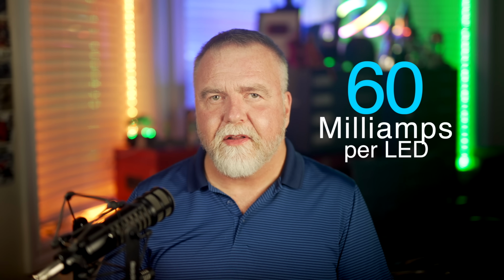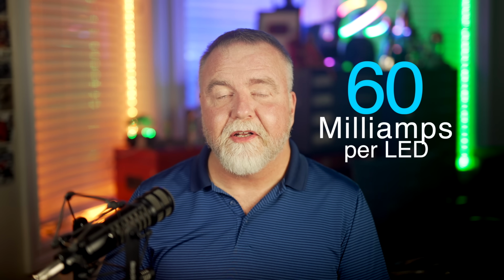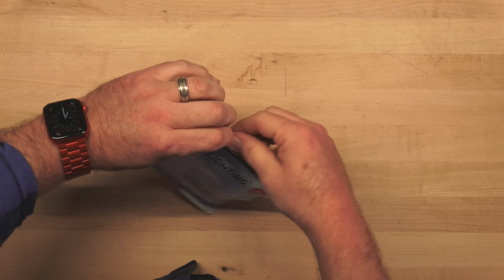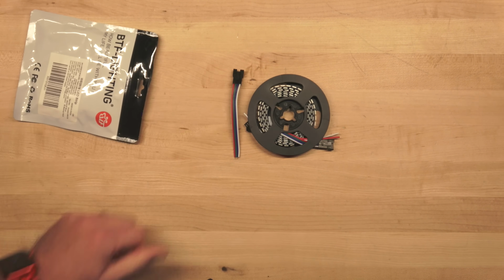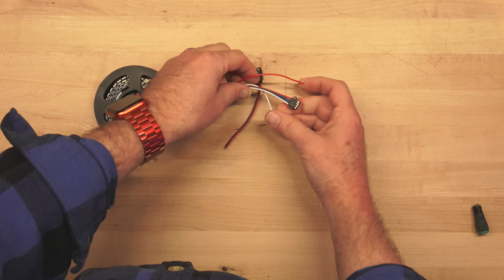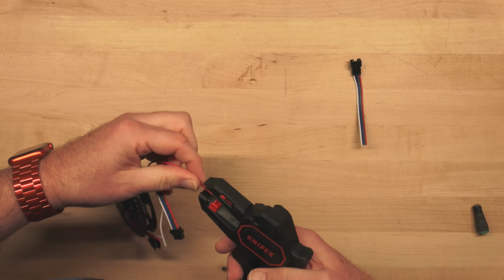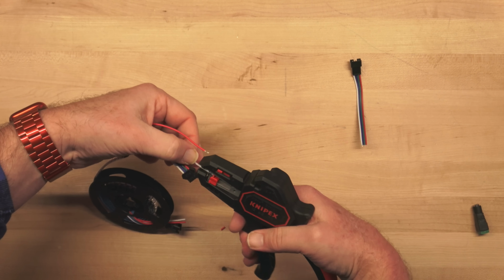Now in theory, you could supply the whole thing off the USB power, but once you get past about a dozen or so LEDs, you're asking for more power than the port can normally supply, so it's just good practice to power the strip independently. To do that, I'm going to connect a female barrel jack adapter to the red and white lines of the strip, which are power and ground respectively. Then I can simply plug the strip into a power brick of matching voltage. Nothing will happen yet when we apply power because without any data, the LEDs all default to the off state.